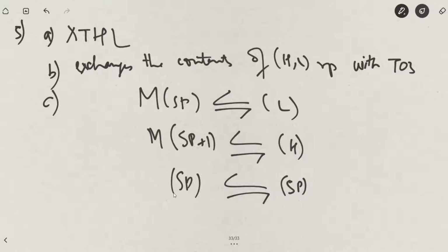You can say this is a combination of both push and pop being carried out by the same instruction. On one hand it retrieves from the stack, and on the other hand it sends back to the stack. The opcode will only consume 1 byte, so there is no other data byte associated with the instruction here.